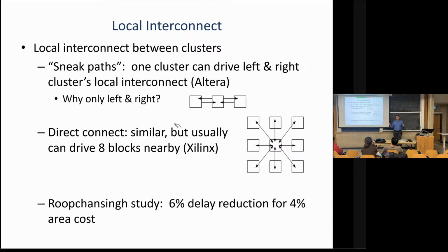And AMD's aren't. So what that means is in the larger, more expensive, this isn't true in like the Cyclone class FPGAs, they're generally not repairable, but the Stratix class, Agilex class, they have big die sizes. So the odds of a defect landing somewhere, making the die useless, is reasonably high.